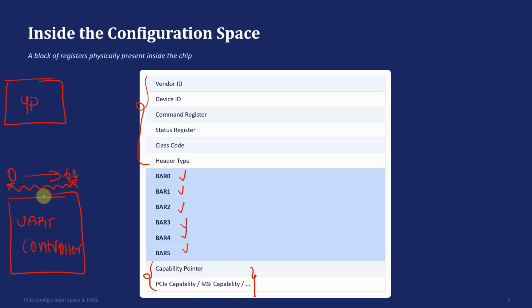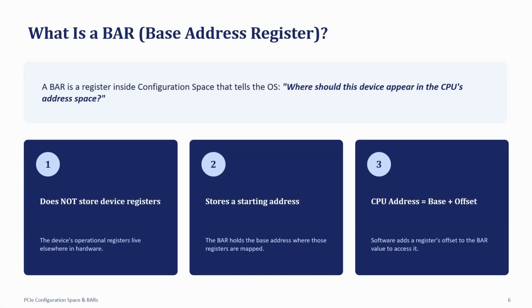My processor cannot exceed or go below the addresses which were specified for a specific controller. I can have multiple devices connected to my processor, and if my processor wants to communicate with any particular device, I am going to have a set of fixed addresses which my processor is going to use to establish that particular connection. Now, who is going to provide these addresses to my controller, how is the processor going to utilize these addresses, and how is the processor going to know what the starting address is and exactly which address should be used? This is what the BAR is used for.